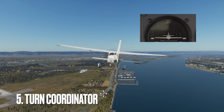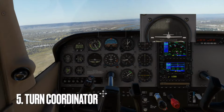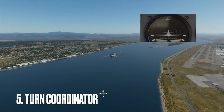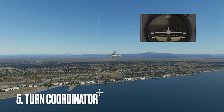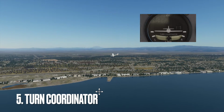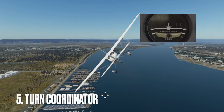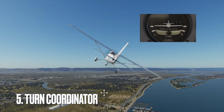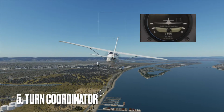The turn coordinator indicates the rate of turn and coordination of turns using a miniature aircraft symbol and a ball. Pilots use the turn coordinator to execute coordinated turns and maintain aircraft control during maneuvering. When making a turn, the turn coordinator helps the pilot coordinate aileron and rudder inputs to maintain balanced flight. Coordinated turns are essential for preventing slips and skids, minimizing drag, and maintaining stability during flight.